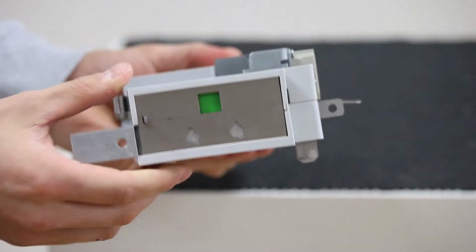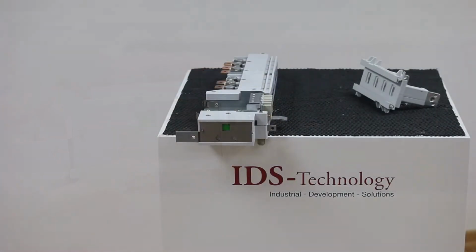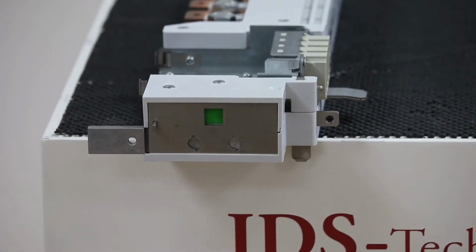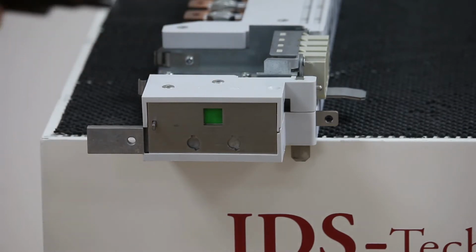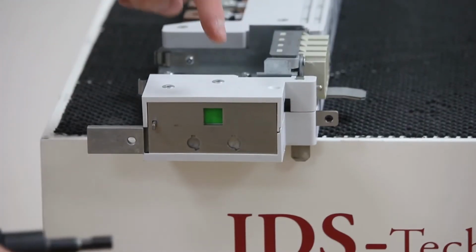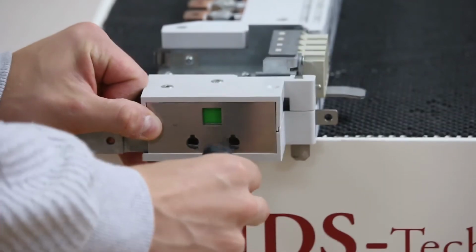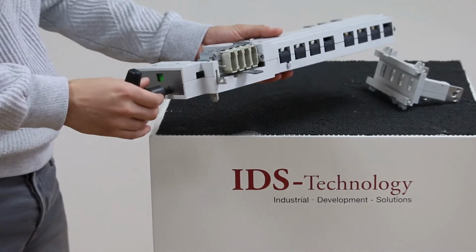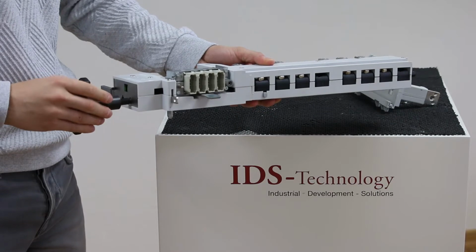In the front it has the mechanical interlocking and operating holes to drive the gear. To move to operate position, starting at disconnected position, showing label green, insert the operating key with its nose at 12 o'clock into the hole on the right. Push the key and turn right until reaching the end position.